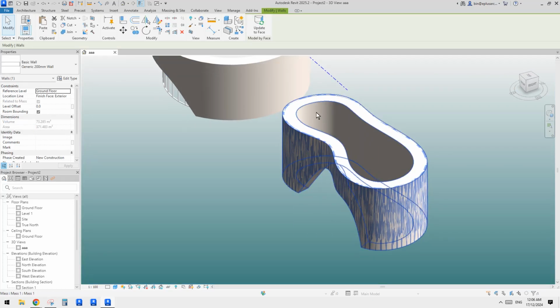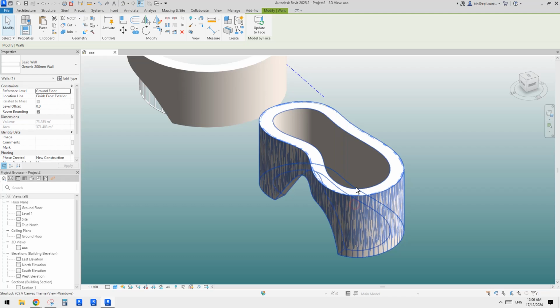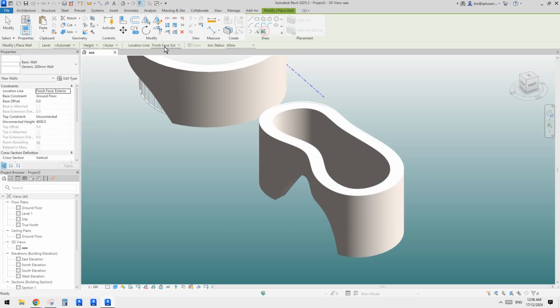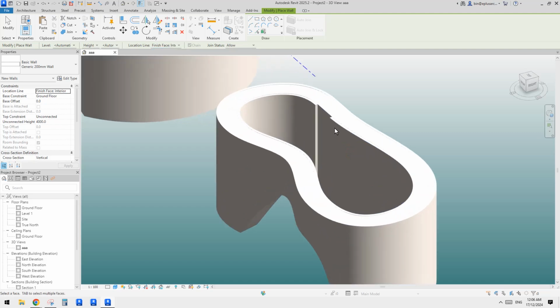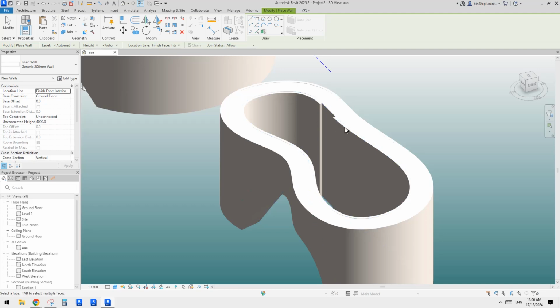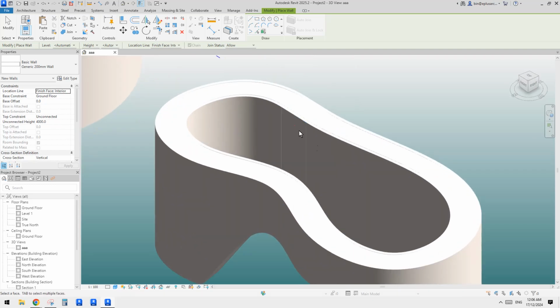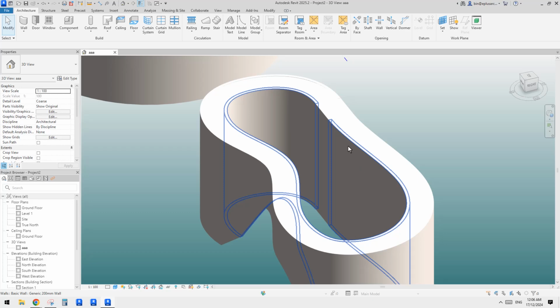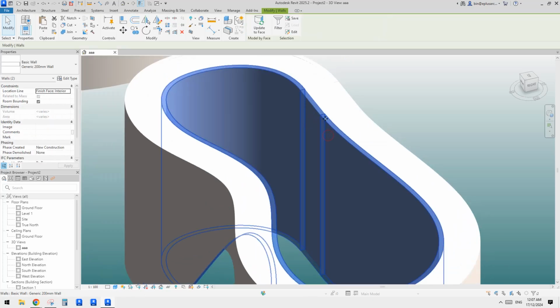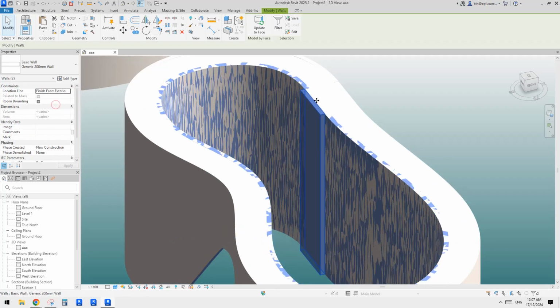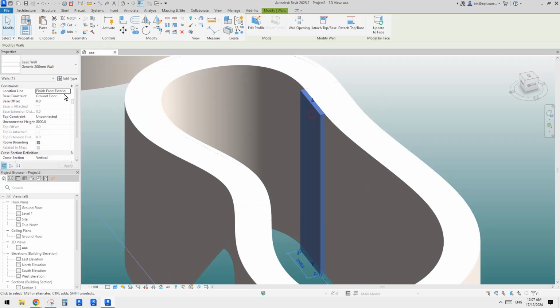And sometimes when you create a wall, so CS, let's create similar, pick a face. If you choose the location, or if you choose finish face interior, it will be placed onto the other side. So you can see instead of overlapping with the mask, it will be placed on the other side and also here as well, right? So these are the options, and also you can always, after you place it, change it to exterior. Oh, what's going on here? Oh, doesn't work.